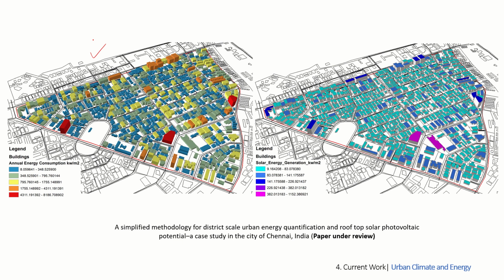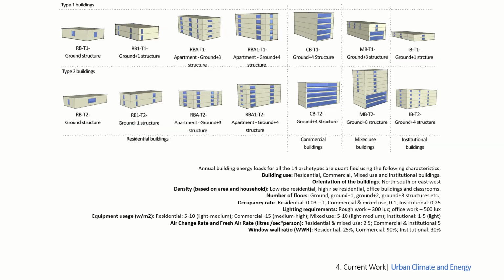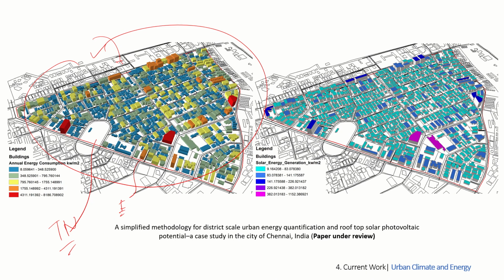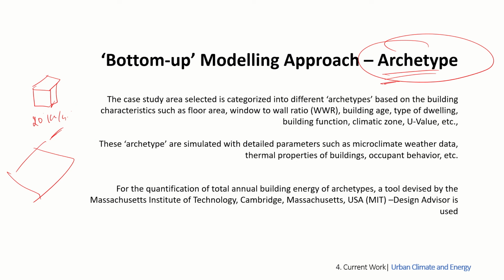I think you must have seen the same image I showed you some time back. This is part of T Nagar. Okay, I had that base. Now I wanted to do an assessment of the total energy consumed by this particular layout. I already have individual building level information. I just wanted to know which building is performing how, what is the energy consumption of each building unit, and so on. It is not possible for us to do individual building models. What we do is apply a technique called archetype, where we